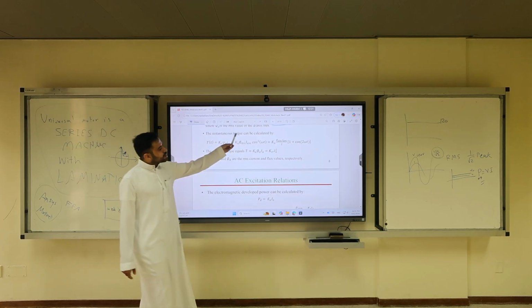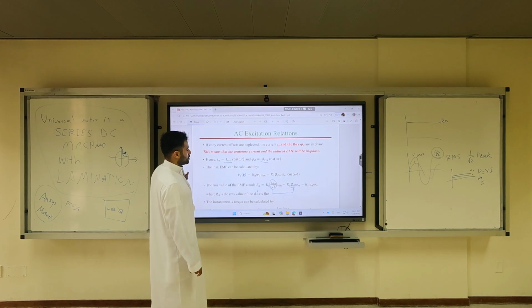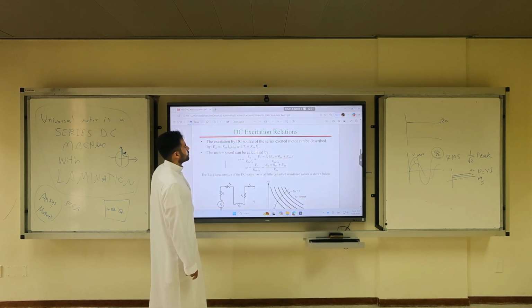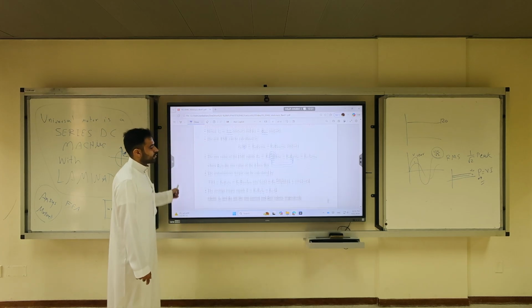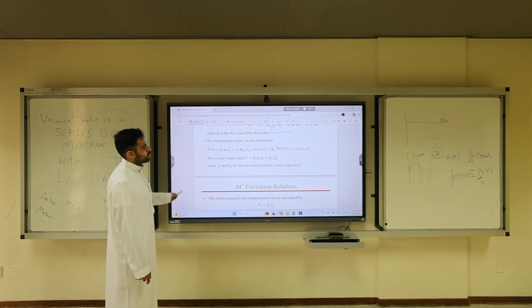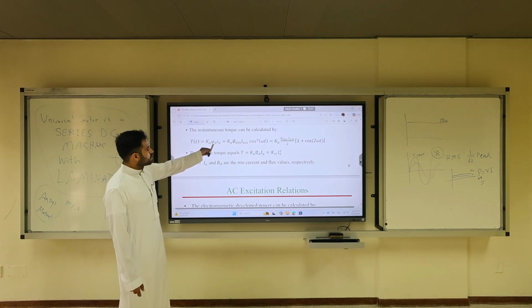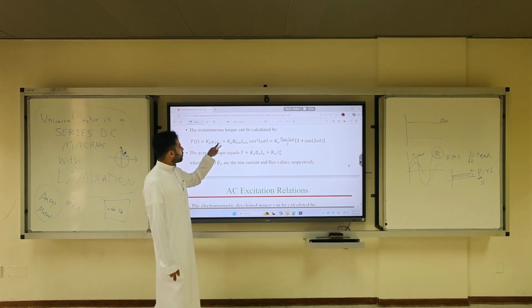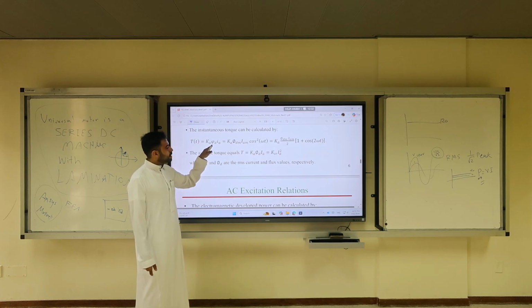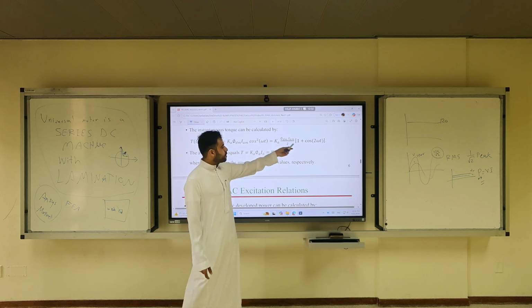The instantaneous torque can be calculated by applying the torque equation K flux IA. This is for DC machine. We had it before. If you do the equation, you will find K times the flux times IA. Write the time domain expression. You get cosine squared. One from IA, one from phi sub D time domain, not RMS. Do the trigonometry, math 002.